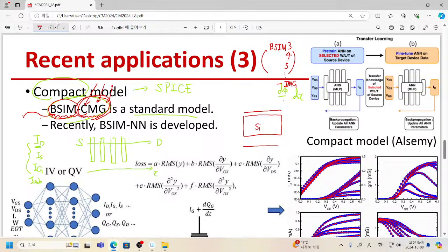This is a silicon, and it has top oxide and bottom oxide, and here we have top gate metal and here we have bottom gate metal, and there is no guarantee that the gate voltage applied to the top and the gate voltage applied to the bottom are the same.